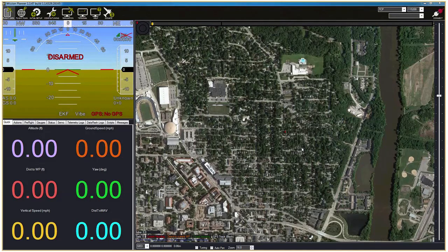Mainly here, this is the flight data tab. You just have flight data, flight plan, initial setup, configuration tuning, simulation, and terminal if you want to write some custom code here. Flight data, if you have it connected, this is your artificial horizon. It'll show the aircraft's orientation, speed, altitude, and rates for both of those. Up on the top here, you have a directional, your compass, and bank angles.